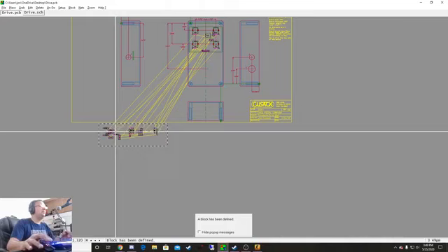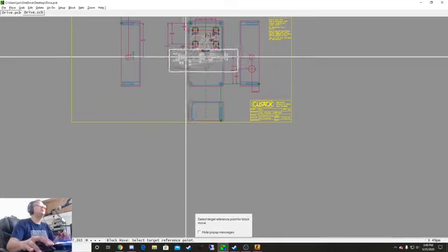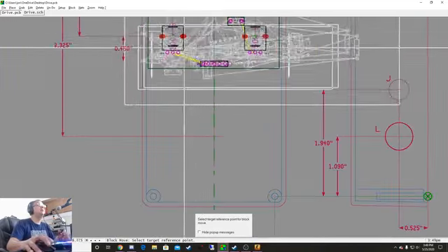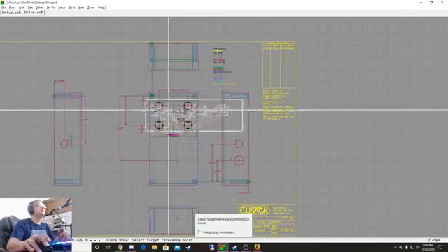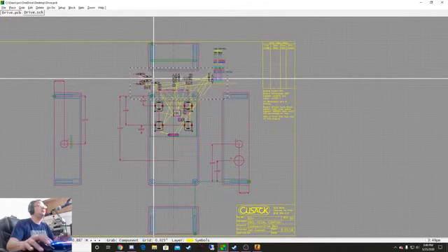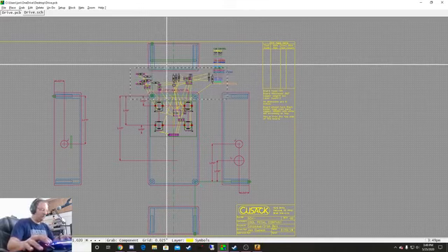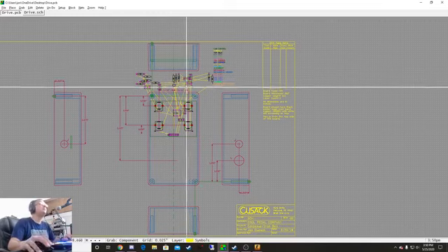And then you click one more time. The third click is where you're going to grab it from. So when I do block move, BM, for block move, it's going to move them from the point where I clicked. So what I'm going to do now is set those up here. And then BE will take that ring away, so the block will be flashing forever if you don't take it away. So BE is to get rid of the block.